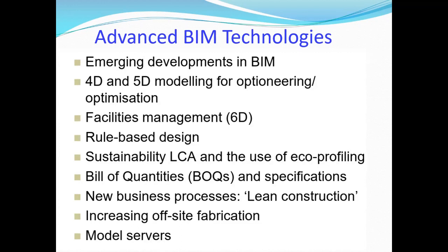Okay, these are the advanced technologies. People are now talking about 7D and so on. I'm not familiar, but basically the Ds mean different roles. When the consultant has a role, we call it 3D. When the contractor is involved, we call it 4D. When the facility manager is involved, we call it 5D. Then they take it to an advanced level. If you want to demolish this building, they call it life cycle analysis. For that analysis, they call it 6D and so on.